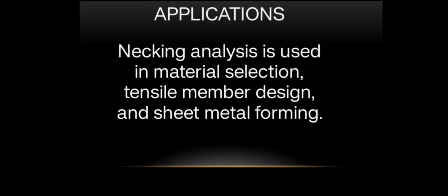Next, the application of instability in necking. The necking analysis is used in material selection, tensile member design, and sheet metal forming. What I'm trying to say is that it is used in designing ductile materials and sheet metal forming operations. Its main point is understanding the maximum load capacity of the material.